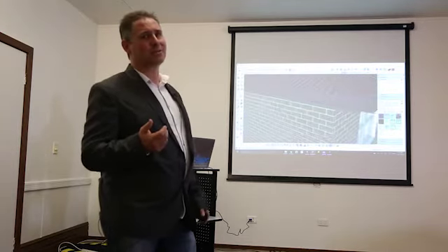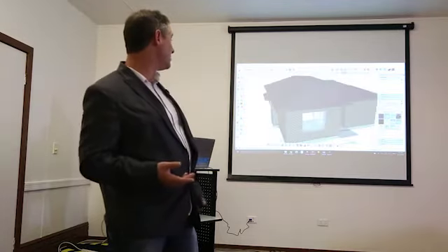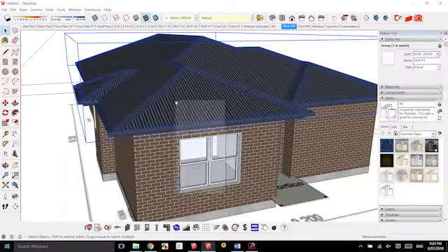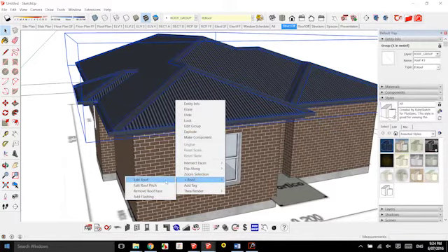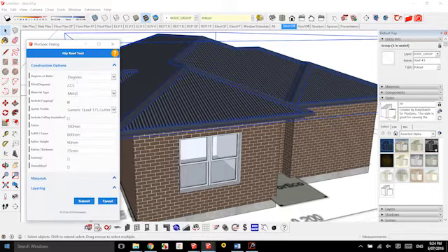We're skipping a few steps, so we already told her that it was 600 overhang. But if you want to go back and maybe, Grant, if you want to change it to a different overhang, make it a small overhang so you'll see the drop off. Edit roof and change it to a tile roof. Choose an alabaster concrete tile and, I don't know, 450 overhang, go submit from there.